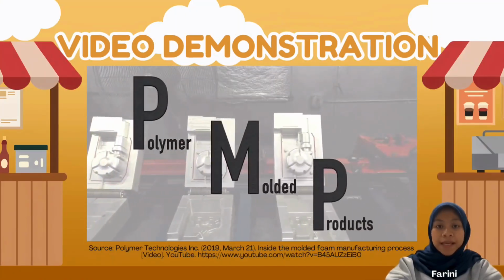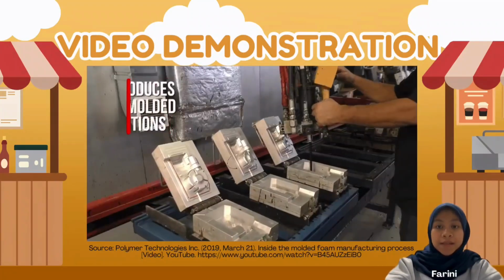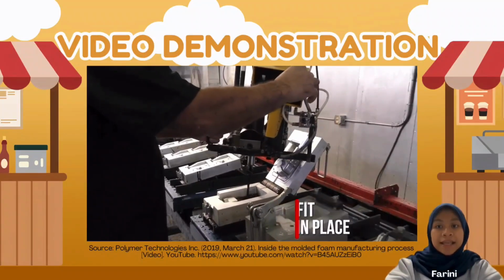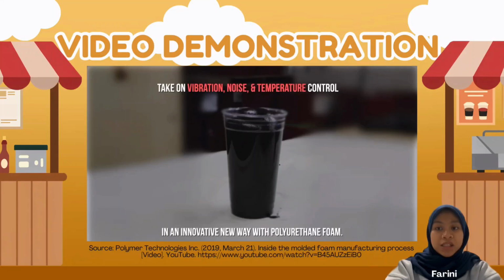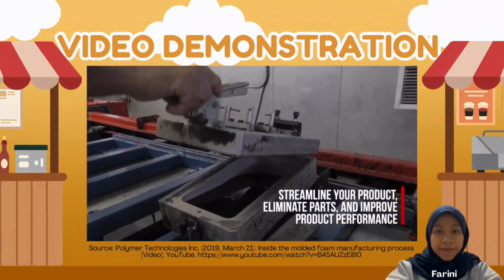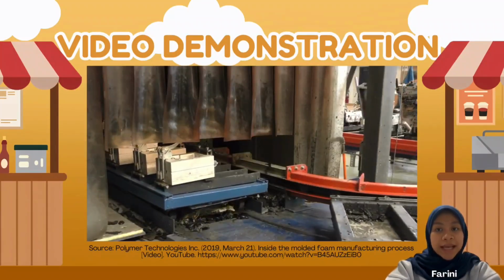Next, I will explain how the foam injection molding process works. The process starts by feeding plastic pellets into the injection molding machine, where they are heated until they melt. A blowing agent is added to create tiny gas bubbles within the molten plastic. The material is then injected into the mold cavity under controlled pressure. As it fills the mold, the gas expands, forming a lightweight foam core while the outer layer remains solid and smooth.